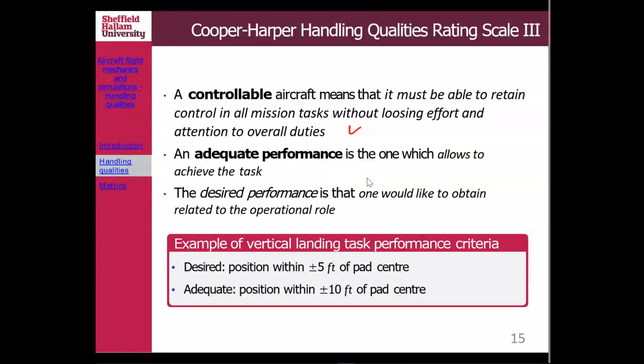And obviously, the question here is, how good is your aircraft at achieving that 30-degree bank angle? I think I mentioned a few times already, if it's not in your tutorial sessions, when you do that, perhaps it's good to see, for example, a record of the bank angle. If you could just put the time history of your bank angle, for example at 30 degrees, then let's see how good your aircraft performs at holding it at 30 degrees, right?